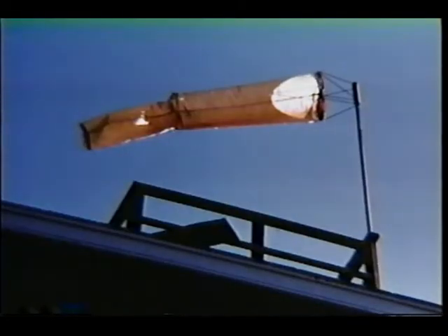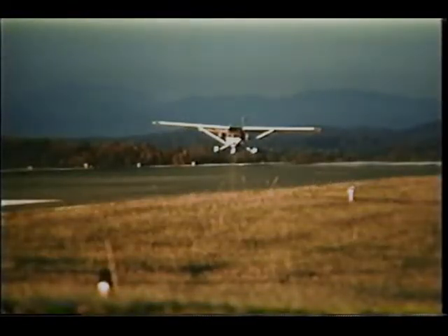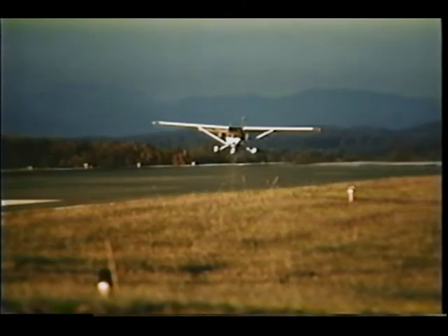The second is when strong, gusting winds are present. We'll address that problem when we talk about winds in a few minutes. And the third is when you're trying to land with an unwanted load of ice. Under such conditions, your stall speed will be much higher, and you've got to carry extra airspeed. However, carrying extra airspeed on short final for any other reason is like carrying a false security blanket, and you're only creating an invitation to land long.